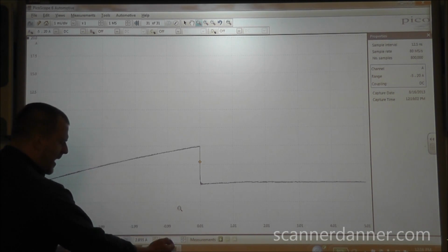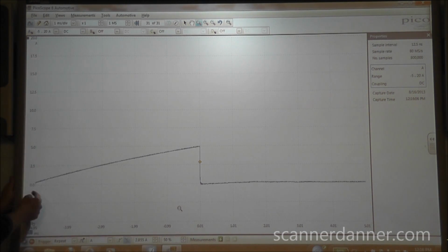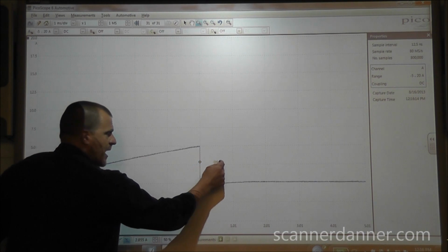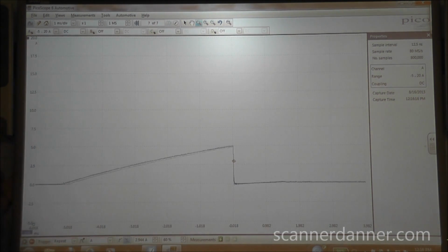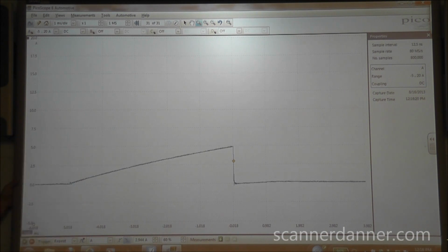And then the delay, which is right here, this 50%, that's just where on the screen. You see how I can't see this section of it right here? There's a couple of options that I could do. One of them would be just take your trigger and add some delay to it, which pulls it away from the edge, and then you can see the whole pattern. If you don't like where it's sitting on the screen, throw some delay into it. So trigger level, trigger slope, trigger delay.